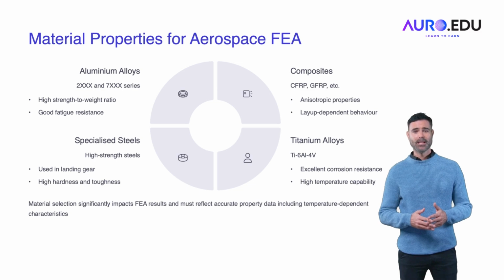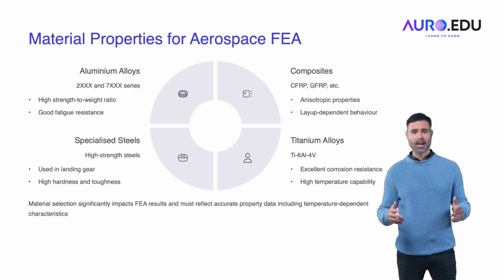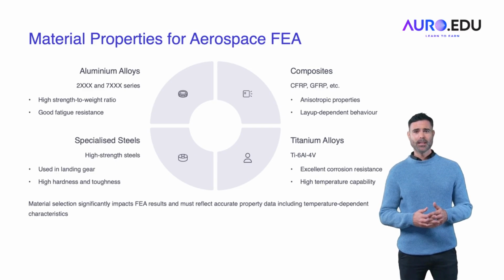Titanium alloys like Ti6Al4V are used in high-stress components due to their excellent corrosion resistance and high-temperature capabilities. Specialized steels are used in landing gear and other high-stress parts for their high hardness and toughness, ensuring durability under extreme loads. Proper material selection based on temperature-dependent properties and real-world performance data ensures that FEA simulations accurately reflect the behavior of components in actual operating conditions.